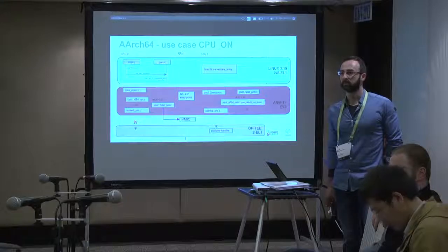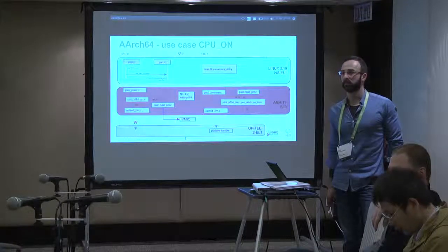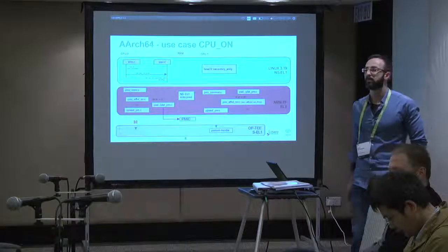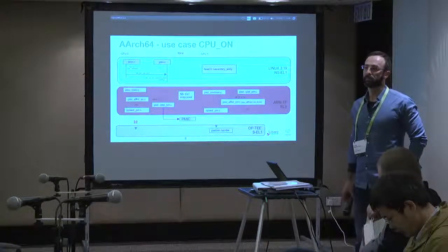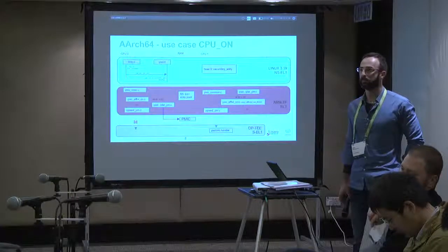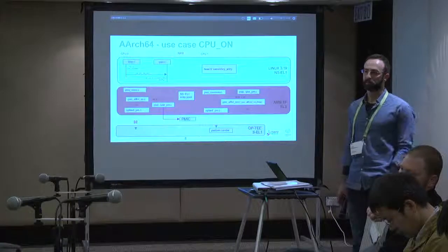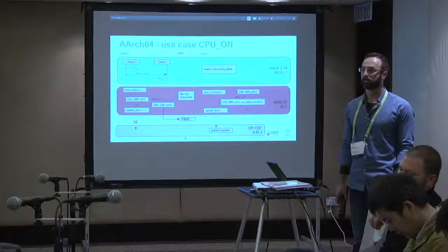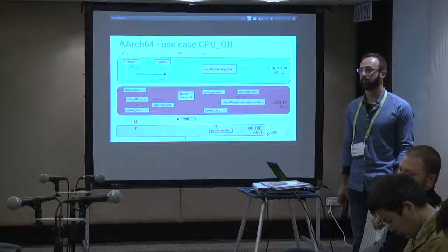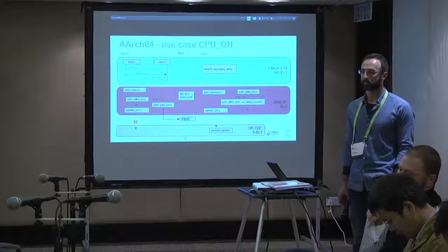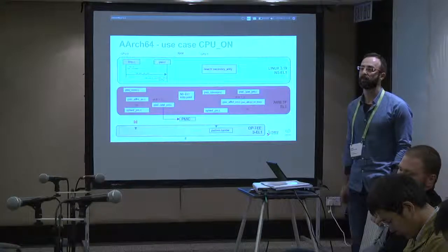I'm thinking that this idea of an OS initiated mode would kind of help you, because the OS knows exactly what state it's going to power down to, so it could actually talk to the power controller and then issue an OS initiated shutdown. And if that isn't the state you can achieve, you then have to tell the power controller to revert the previous request. It's going to be very challenging to do it in a way that is both robust